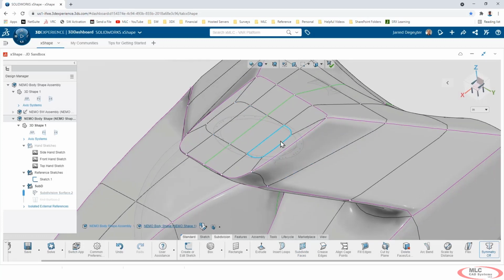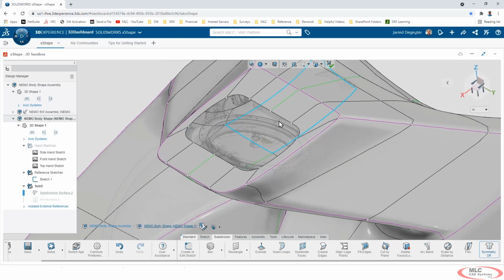So from here, in this case, I'm just going to come in and select those faces and delete them. And what we're doing basically, instead of working with a solid, I'm working with some actual surface modeling. Now here's another one of those really cool techniques that we can use to mask select entities. I'm just going to select with a double click.